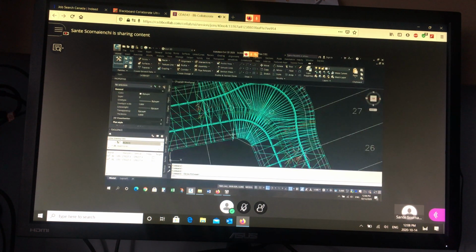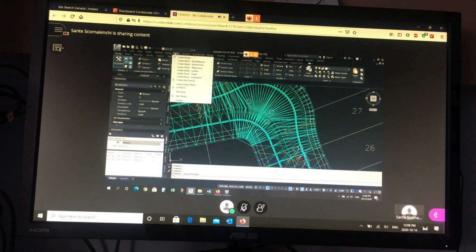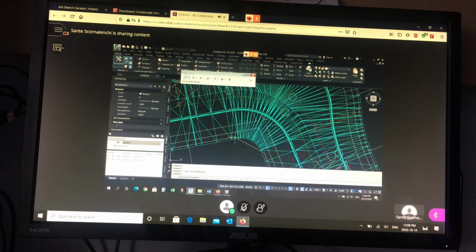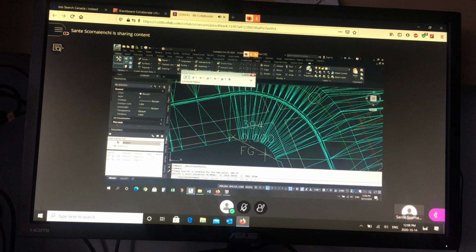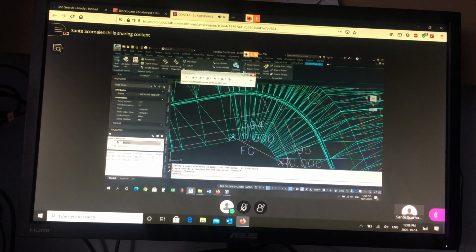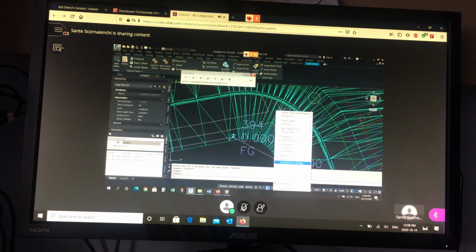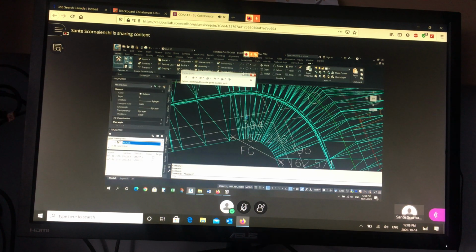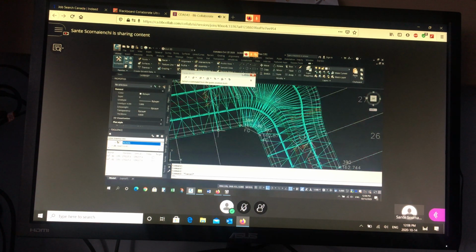Okay? And then if I want to create points, manual, I'm going to put one here, and these two elevations are now inside the surface. Elevation from surface, my design elevation comes from that road. I get numbers. And now that's my lot grading and so on, right? So all the front lot corners.